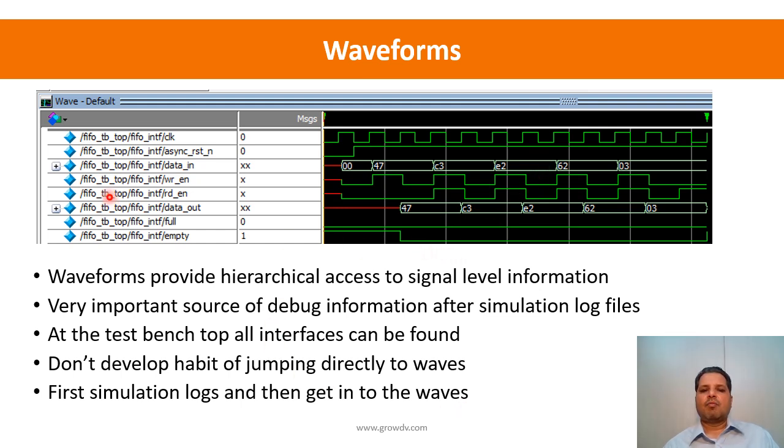waves. And one point that I want you to notice in this waveform is that this write enable is never continuously high, right? And there is a reason for this, and this is because of the way we have used the clocking blocks. So there will be one of the exercises where you will have to write the push drivers and the pop drivers such that this idle period that we have over here should be eliminated, right? So that will be the one exercise that you will be doing. So this is how you utilize the waveforms.